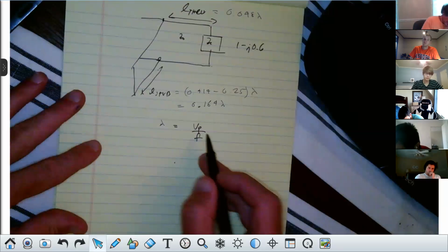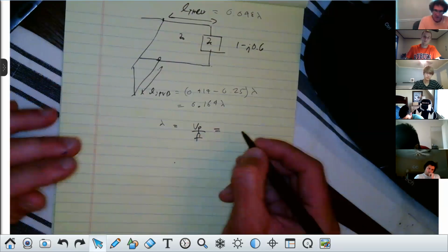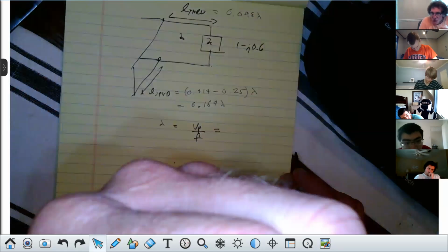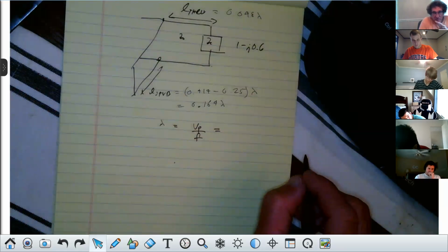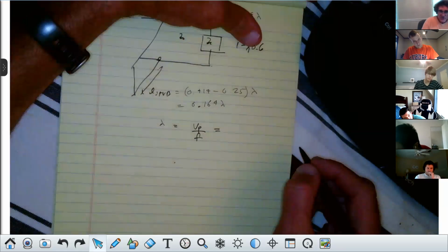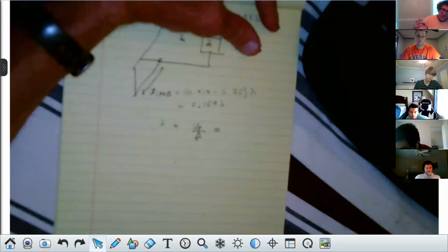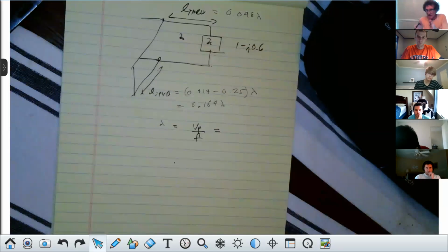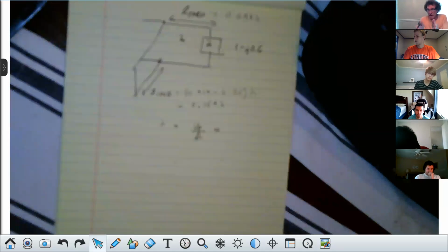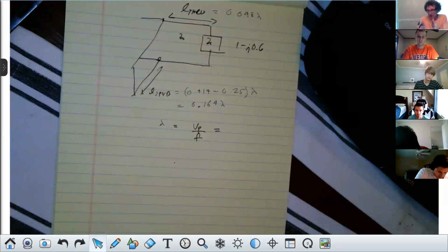Now, phase velocity on a transmission line, and I want to tell you this, is usually given as the speed of light, but not always. Here's the way it's typically given, because when you have a dielectric between two conductors, that dielectric can have an epsilon relative greater than 1, and that will slow things down. Now, I'm going to just put this down here for you.